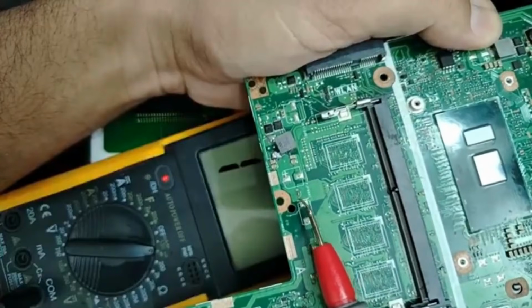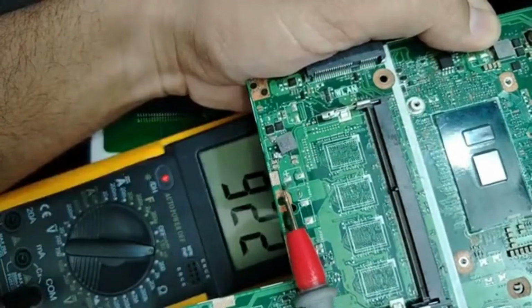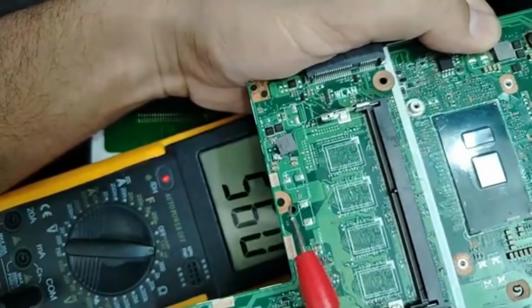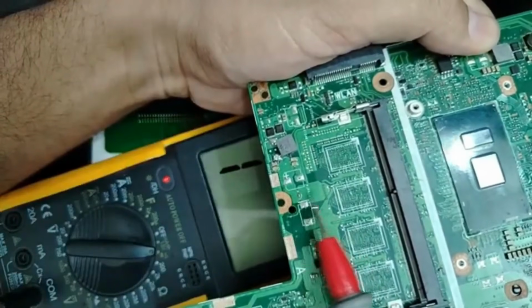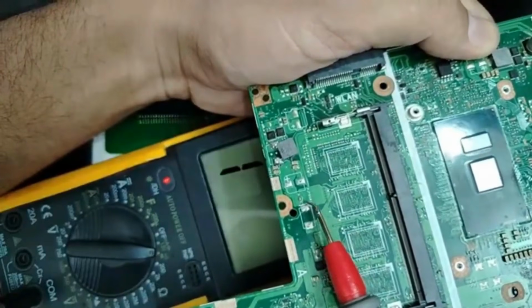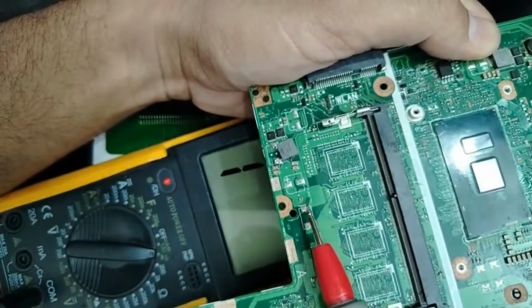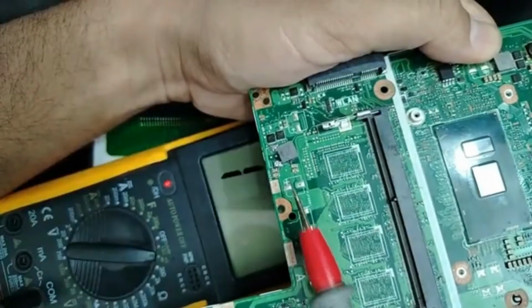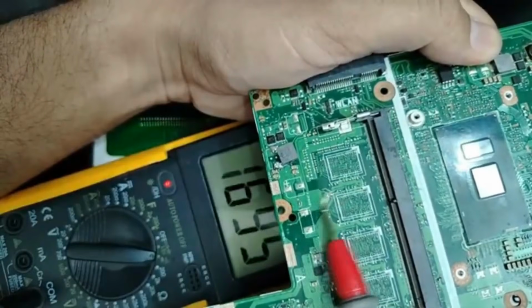We have this guy here. Do you see this one? If we remove it, we will separate this side, where we have the ceramic capacitors, from this side, the motherboard, because this point means the motherboard goes. The voltage here is connected to all the motherboard. If we remove this one, we will separate these 2 stages. If we find the short here, the short will be in these 4 ceramic capacitors. If we remove this one and we find the short gone, it is not here, it means it is in this side.